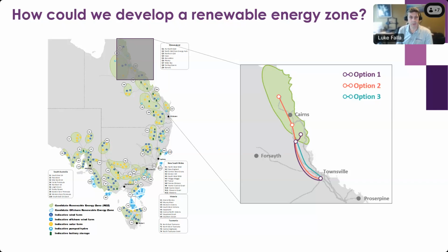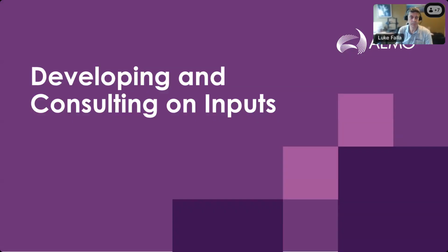So we typically find you can get a lot of wind and solar together, really increase the utilization of the network, and accept 3 to 4% curtailment of that generation before needing to upgrade the networks. The reason we're doing the linear expansion modeling is again for the runtime on these aspects. So I think, as everyone's talked about before, there's a lot of data, and this takes up a lot of our process, really, consulting and developing these inputs.